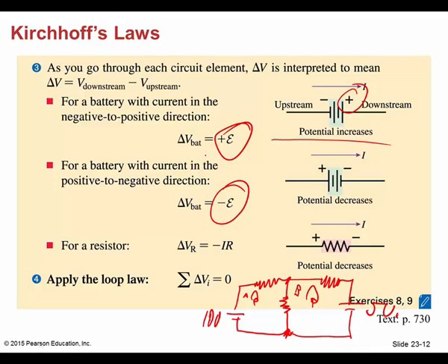Now, the opposite applies on current. Whenever you're going through a resistor, you are dropping voltage. Current times resistance is voltage, so you are dropping voltage. You're using energy; the resistor is absorbing the energy. Now, what if I came through a loop going the other way? Well, notice that we come out on the positive side, so we are adding voltage.